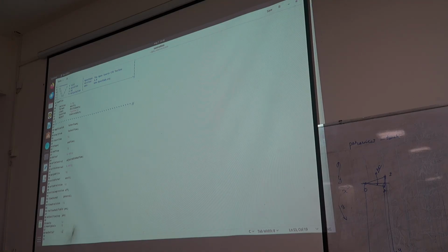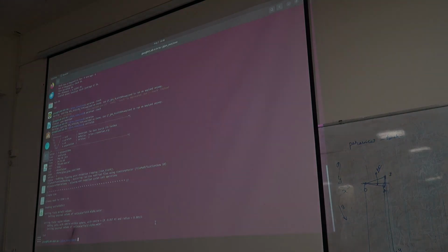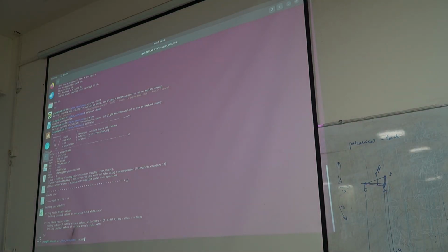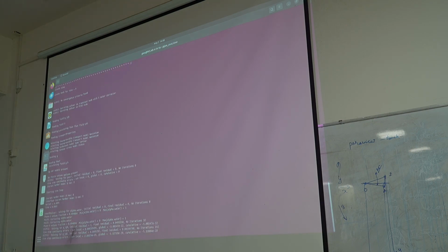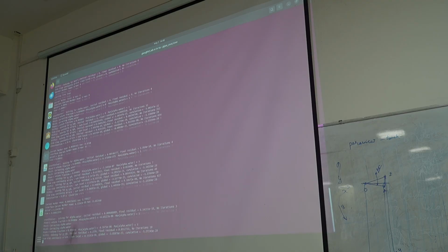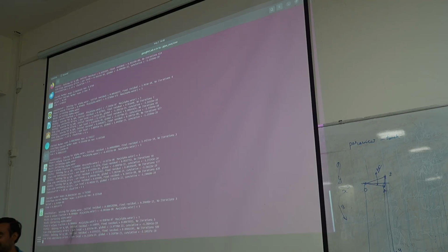After this, what I can do, I can go to the terminal and run the command interFoam, inter with small, then capital Foam. Is this point clear? Now please press enter. You will find this simulation has started running, and of course it's a fine simulation. Okay, so we have a good number of grid cells. It will take a good amount of time.